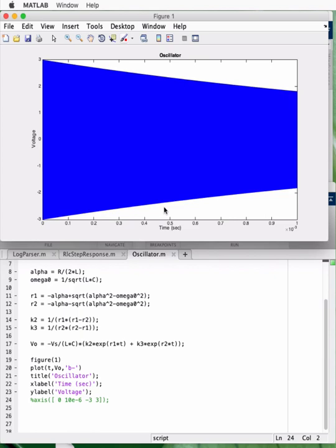And this really gets even worse when you actually want to use the oscillator for something, right? The whole point of an oscillator is to hook it up to something and have it drive a circuit that needs a clock. And even though most logic circuits have a very high input impedance, so they don't draw a lot of current, they do draw at least a little bit of current. And so when you hook up some kind of load resistance to the oscillator, the voltage waveform is going to decay even faster. And so the solution is to not design an oscillator this way, basically.